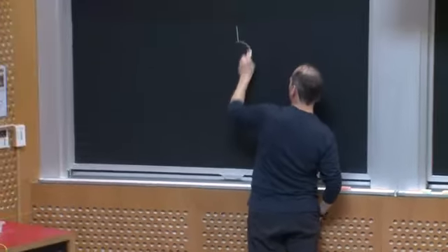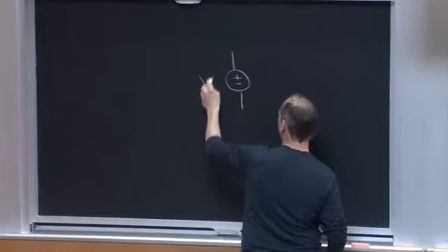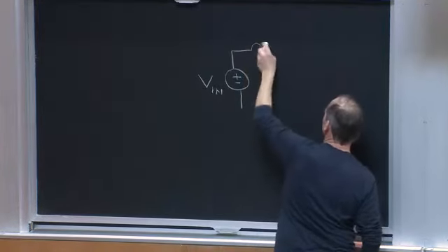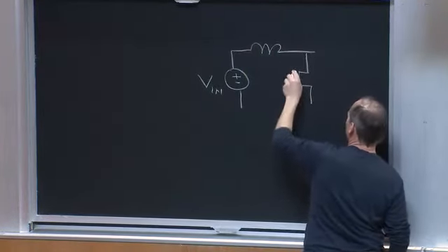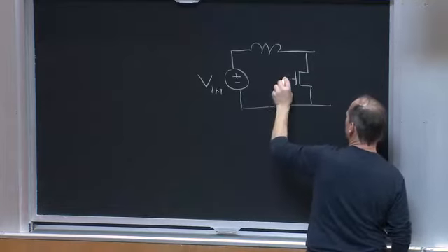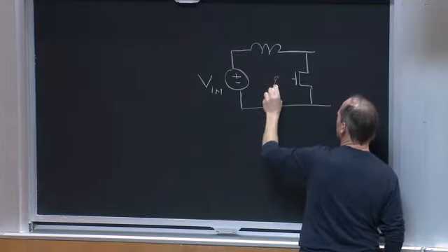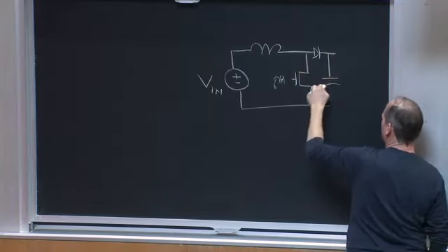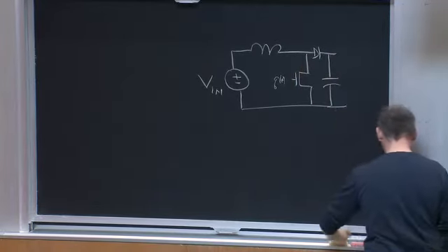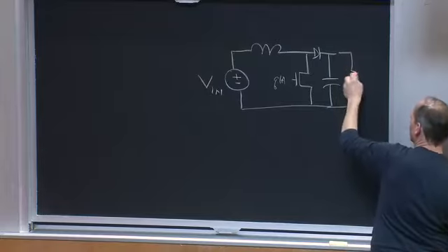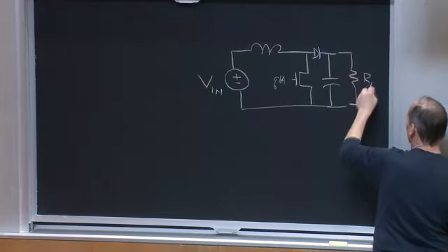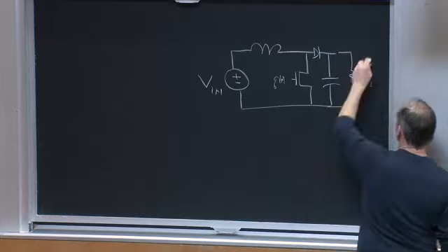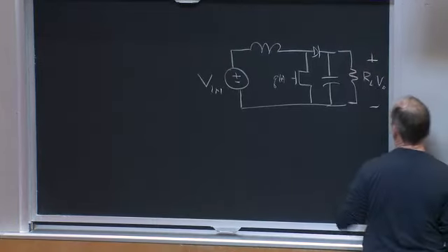So let's think about a power converter. Let's start off with our friendly neighborhood boost converter, right? So maybe I have some input voltage Vin. I'll switch it with some switching waveform Q of t, and then I'm going to have a diode. I will have a capacitor, and the converter ends here, and then somewhere we usually show RL, right? And I have my input voltage and I have my output voltage Vout, okay?